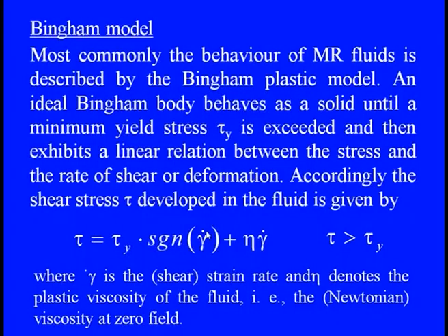So the first model coming under this magneto-rheological fluid damper is the Bingham model. As we discussed in the electro-rheological fluid, when the fluid is under shearing action, it is not a Newtonian feature; there are two features. After the yield limit, there is a clear relation between the shear stress and the rate of shear strain. So here we have a clear Bingham nature. Here also, when we apply the magnetic field on these polarized particles, we can have a similar kind of relations. So the most common behavior for this MR fluid is described by the Bingham plastic model.